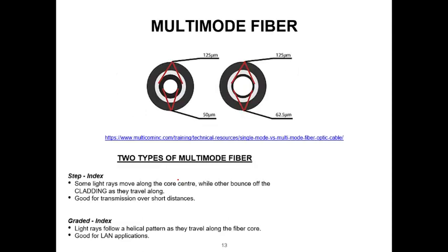The other type is multi-mode fiber. Multi-mode comes in two standard diameters. One is 50 micrometers and the other is 62.5. That's the diameter of the glass core. The jacket here in both cases is 125 micrometers in diameter, and this thinner black part in the center there, that's the cladding. That again is to keep the light within the glass from leaking out.